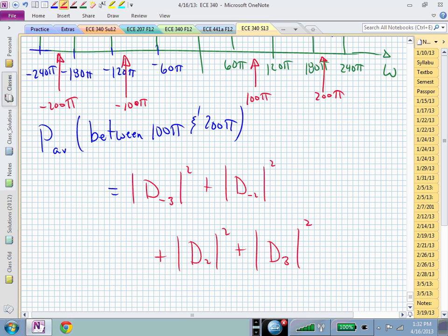But if you look in the book, I think maybe even in that first table, table 6.1, you will see those factors of 2 in there if you start using Parseval's with compact trigonometric. Okay, so make sure you're clear on which of these coefficients you're using to compute the average power or the power in certain intervals. Does that help answer your question? So it's buried in there implicitly, that factor of 2, because now we're dealing with complex exponentials. And that makes for maybe a cleaner looking formula. We don't have to worry about that factor of 2 in there.